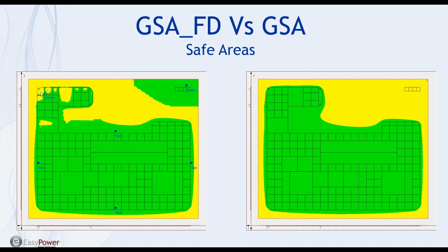And so you can see some yellow holes, which means that the touch voltage is above the limits. This is due to the effect of the drop of voltages along conductors, and drop of voltages can be related to self and mutual impedances. Some tools available in the market neglect the mutual impedances, but this can lead to serious computational errors, also more than 20%.